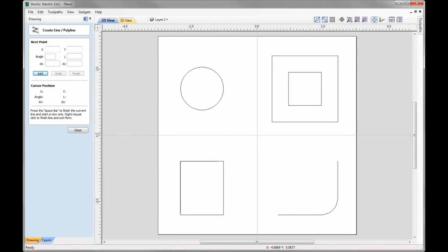So we've looked at the object bounds, horizontal and vertical lines, and angled lines. Now Smart Cursor can also pick up tangent lines. Let's wake up this circle here, and if I move my mouse along, you can see that the software has found a tangent line, and I can click and follow along that line, and click that in place.